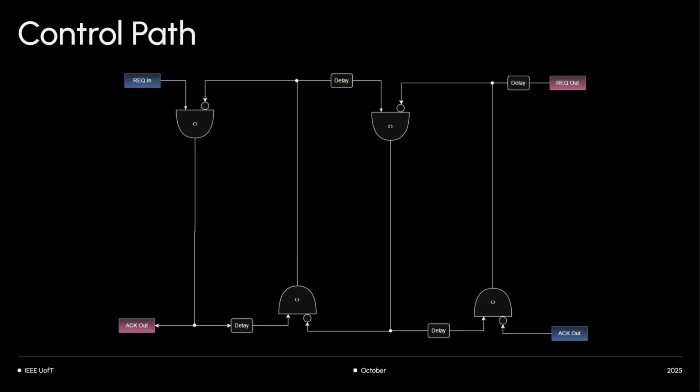So what you do to flush out everything or reset it is just add, as we have flip-flops in here, that's really what's storing the values and driving out these lines. Just connect a separate reset line and pretty much zero them out externally. Don't mess around with the controller. Each one will have a reset line and you just reset it. That's one way to do it. Does that make sense? Okay.